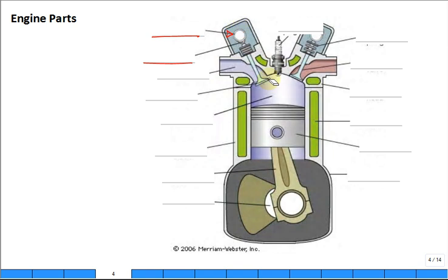Camshaft. And you have 2 of them. Dual overhead cam engine. Hey, we've seen that. A lot of times they only have 1 cam. Here they have 2. What's this thing? Spark plug. And here's a way to get stuff in, and here's a way to get stuff out. That must be the intake and the valve controlling the intake, and this must be a valve controlling the exhaust. That's right. And those look like springs, valve springs.